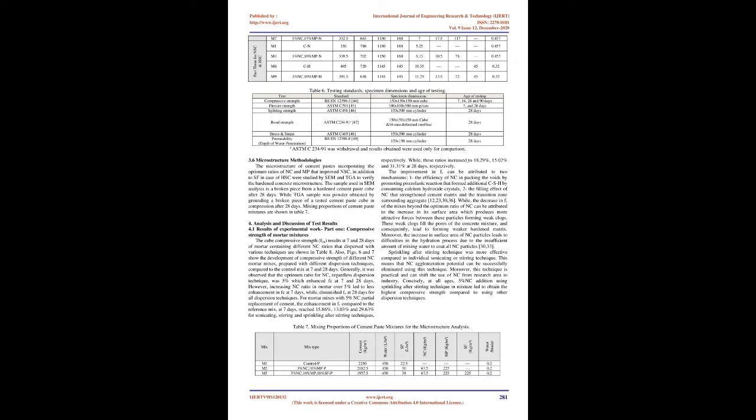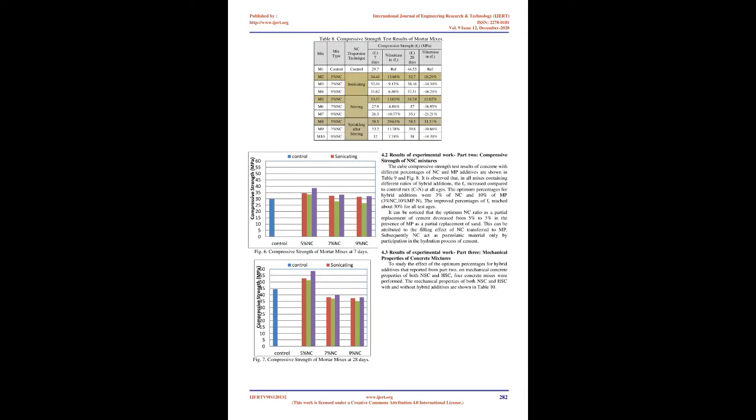3.2 Mortar Mix Design, Mixture Proportions, and Test Parameters. In order to assess both the effect of adding NC as a partial replacement of cement in concrete matrix and the best NC dispersion technique on concrete compressive strength, different mortar mixes were prepared in the lab. At first, standard mortar mixture was prepared according to ES 2421 to 2006, 42 to determine the standard water-C ratio. After that, 70x70x70 mm mortar cubic samples, 6 cubes per each mix, were prepared with variable replacement ratios, 5%, 7%, and 9%, of NC by weight of cement.